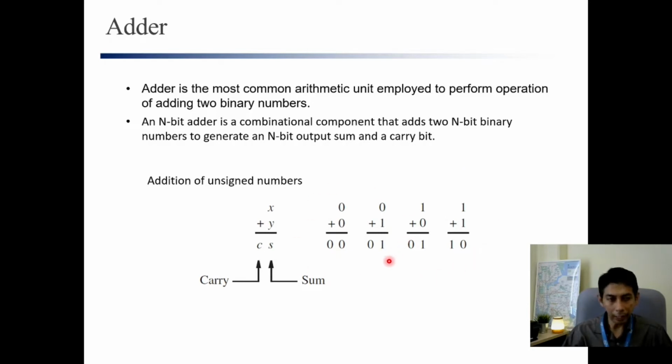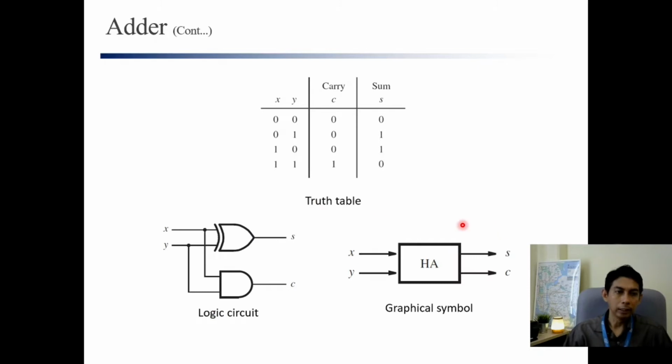If we have these 2 inputs and 4 possibilities, we can create a hardware, designing the circuit starting from the truth table. So the sum and carry we can represent in hardware using this truth table. This is the behavior of the adder.